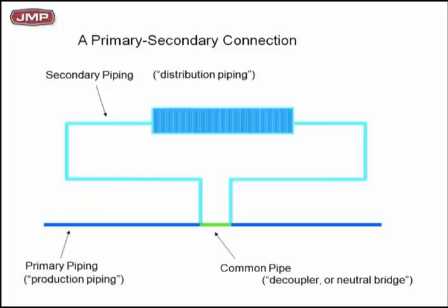Now, what we're trying to do in true primary secondary design is keep that pressure drop as close to zero as you can get. It could be 18 inches or some small amount of numbers, but we want it to be as minimum or as close to zero pressure drop between the two T's as we can get there. Then you see the secondary loop, the distribution pipe on the secondary loop, the secondary load side. Chilled or hot water, doesn't matter. Those are the definitions of what you need to be looking at primary secondary.